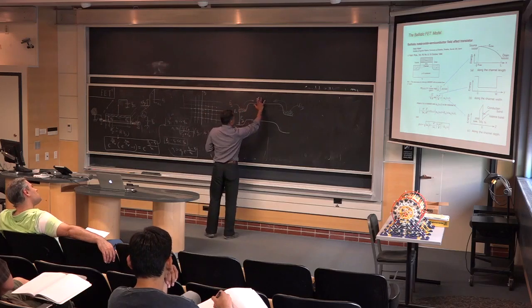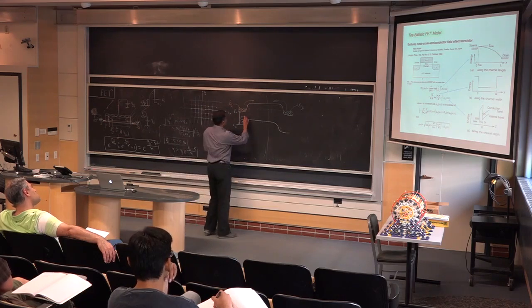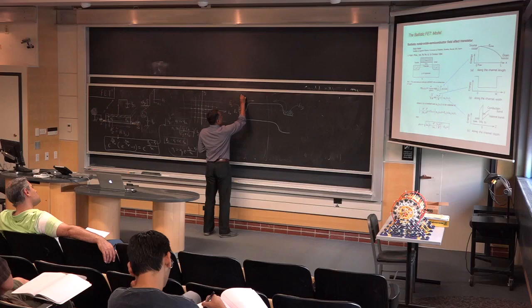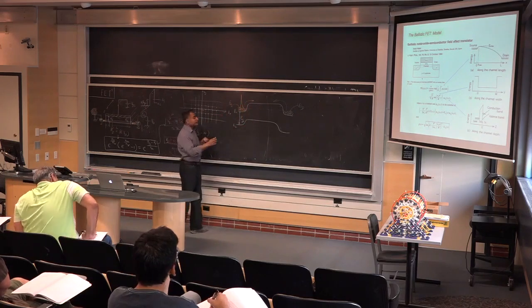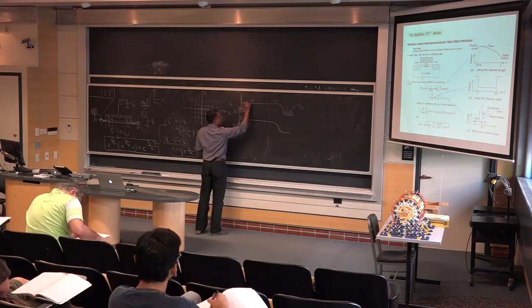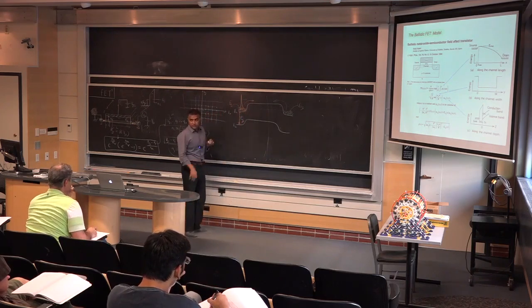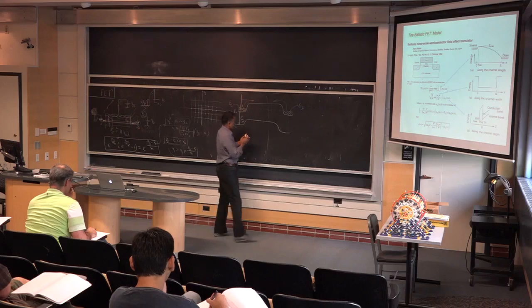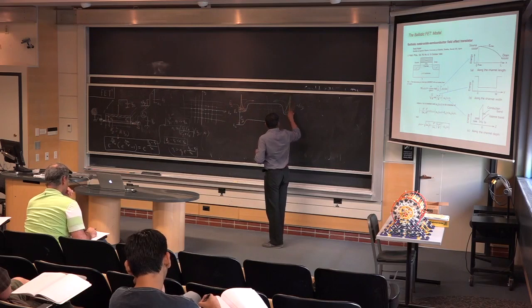So in this picture then, if I were to draw in the K space, this is kind of a critical point to understand. There is a Fermi Dirac distribution, this is the Fermi level, so there is a tail of electrons that goes something like that, right, in the band. And this tail of electrons, for example, at that gate voltage, there is a barrier here, and this many electrons are essentially going to get injected, right? So half of them are going to the right, and that sort of picture. Similarly, here you also have the tail, and again, this fraction is going to get injected.